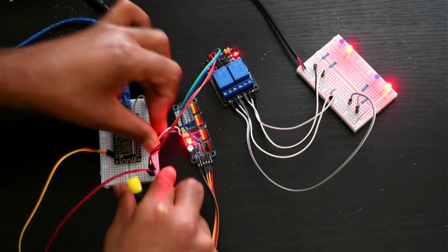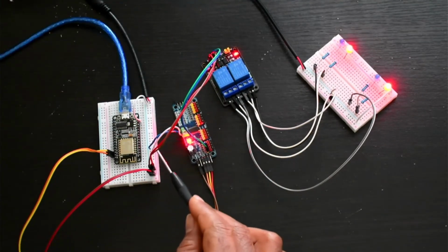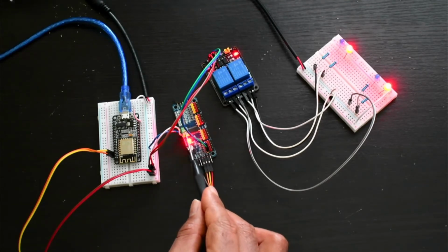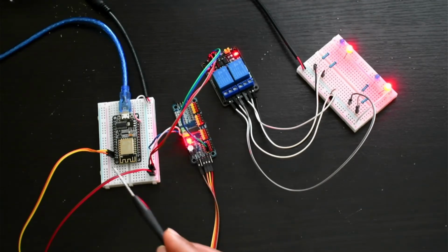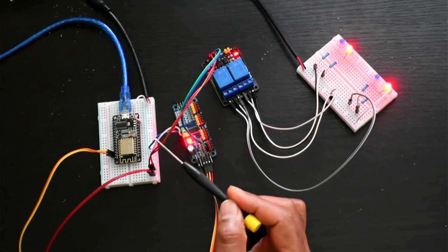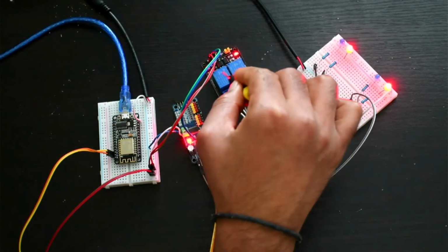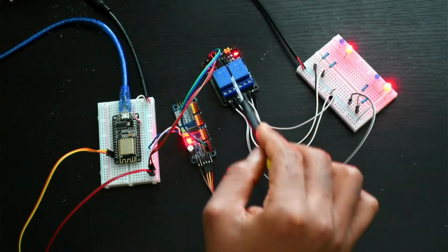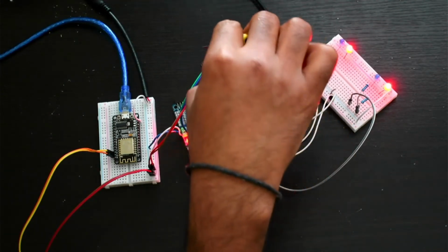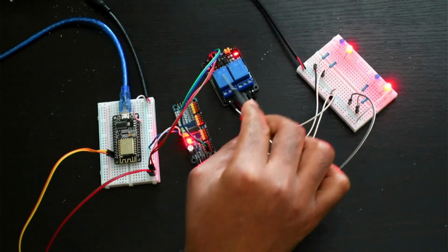And here you can see on the side, this loose connection. Okay. So this blue one is GND and the white one is the 5-volt power supply going to the PCA9685 board. And here you can see this red and brown is carrying 5 volt and GND to the PCA9685 board. And this red and brown is taking 5-volt power supply to the two relay switches here, and this green and blue is taking the input signal for controlling these two relay switches.